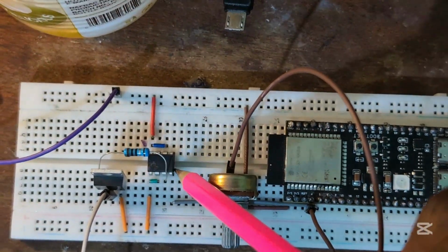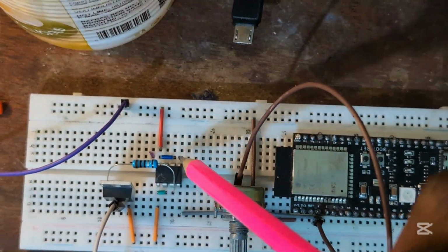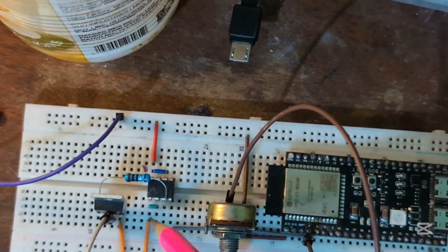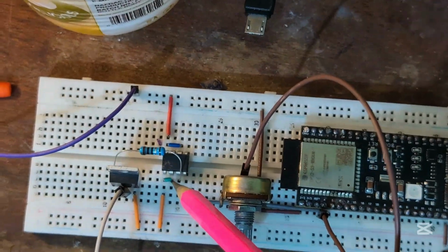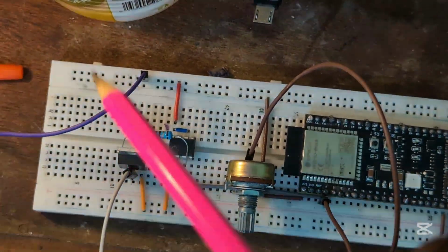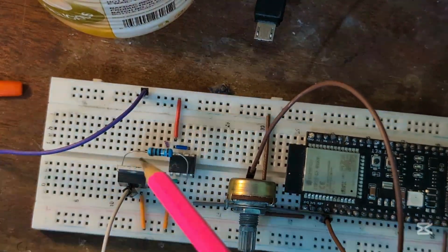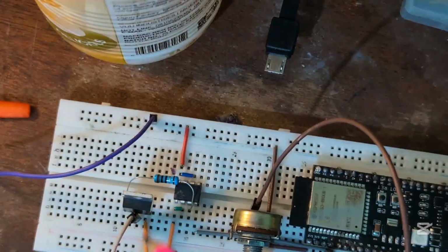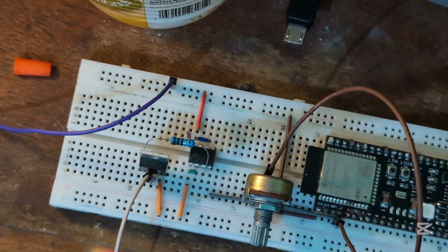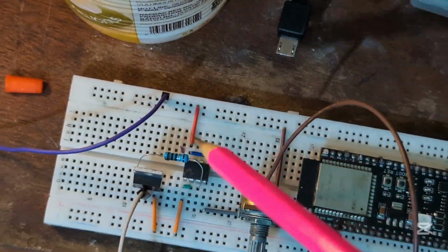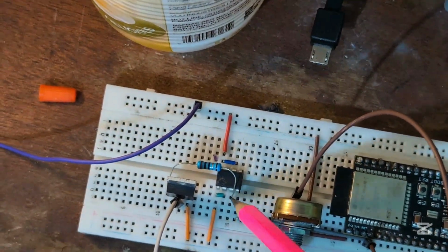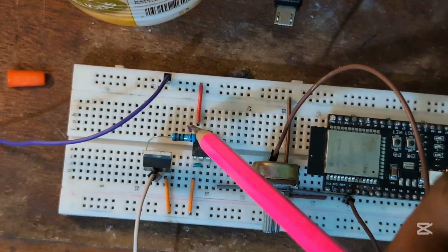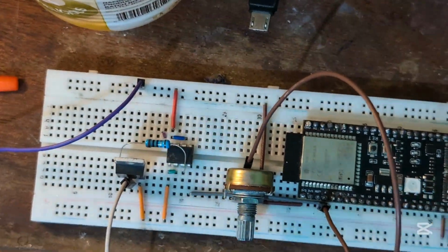So these are pins 5 and then pins 7. So pin 5 and 7 are connected to 12 volts. Pin 1 and 2, according to the schematic I did before, is connected to ground. The drain of our MOSFET is connected to ground too. Source is connected to one end of our load, and then the second end of our load. The gate is connected through this 10 ohm resistor to pin 3. That's the output pin. So the connection is done using this 10 ohm resistor over here.